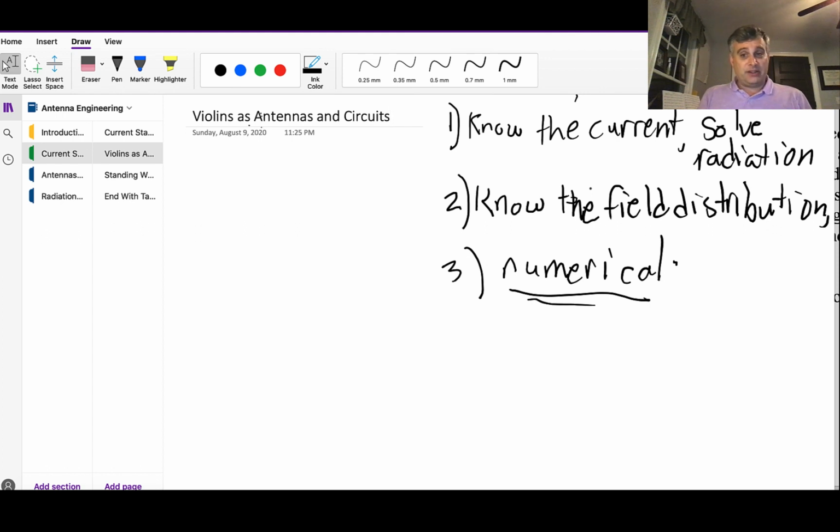And it's a solvable, tractable problem in electromagnetics, but you have to resort to something called integral equations. And that's a fancy word. It doesn't mean equations that you have to integrate. Georgia Tech students have no problem doing that. That wouldn't be an issue at all, if only it were so easy. What usually that means is that the thing that you're solving for is underneath a multidimensional integral. For example, solving for the current on an arbitrary metallic structure. That current is under an integral that you have to enforce boundary conditions on, which makes it very challenging.